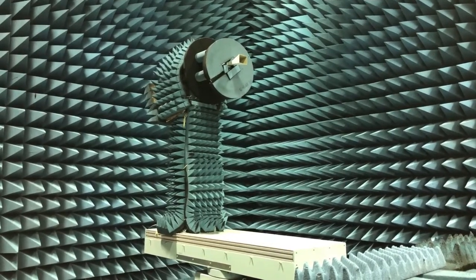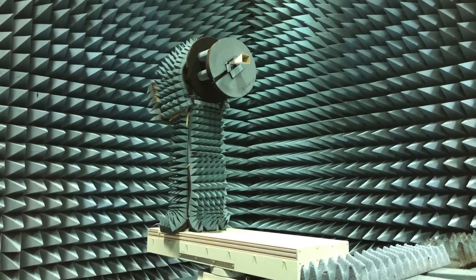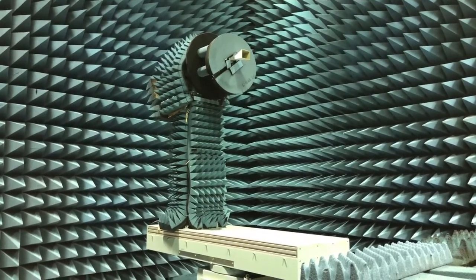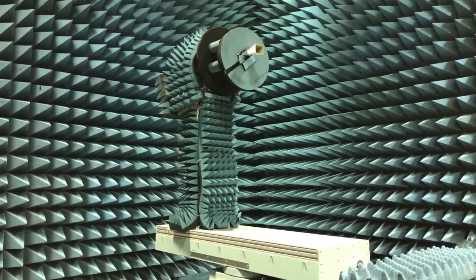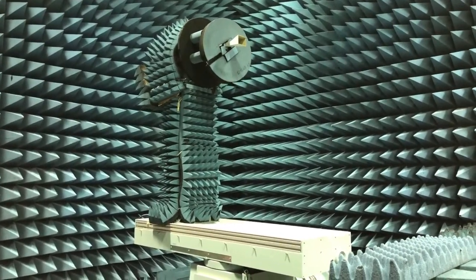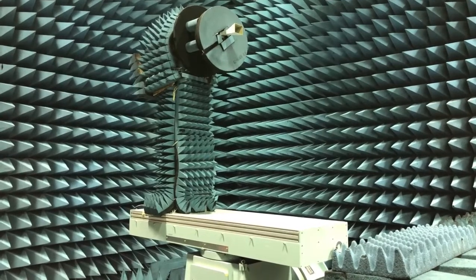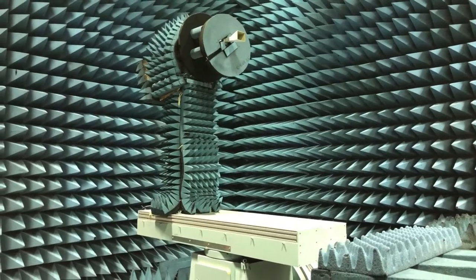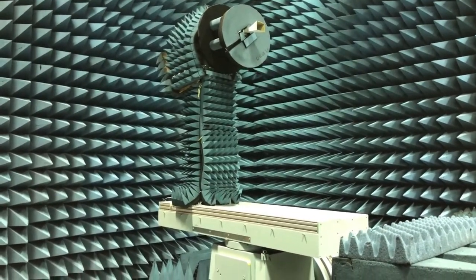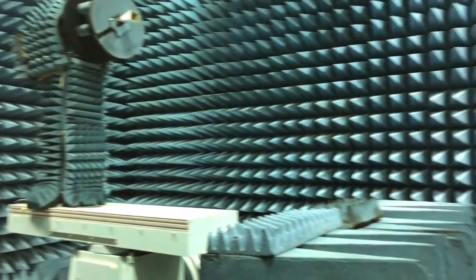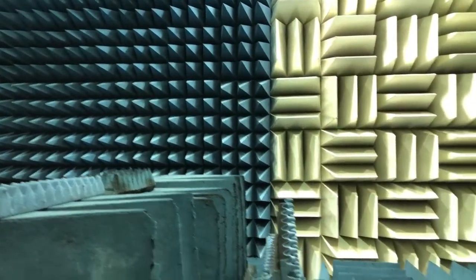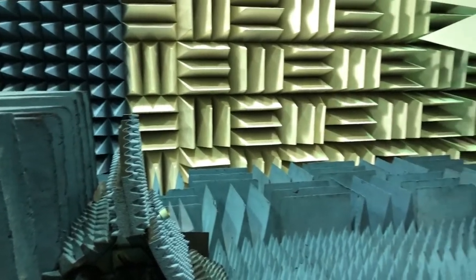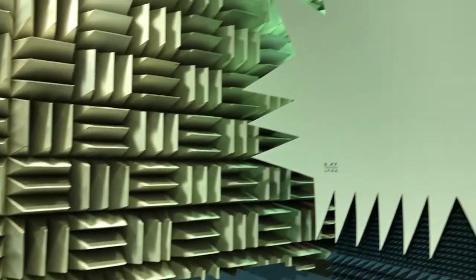Now this AUT tower can rotate in different directions, and you can essentially get the cut that you want. If I want to make a one-to-one correspondence with the training system that we saw, this tower is the tower for the antenna under test, and the combination of the feed and the reflector itself would be essentially the role of the Yagi-Uda antenna that creates the plane wave for us.